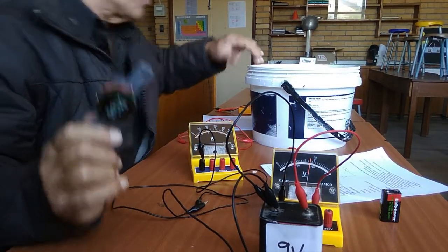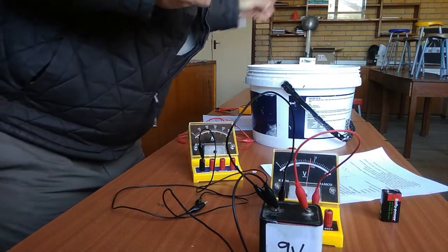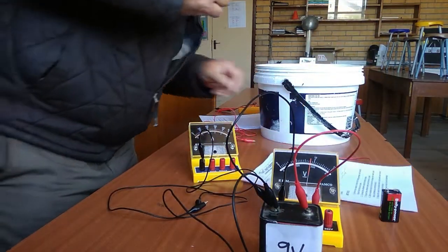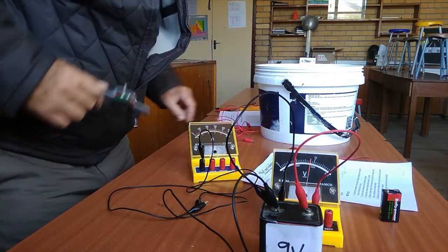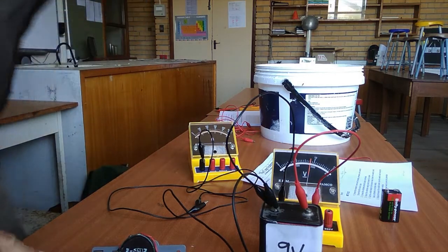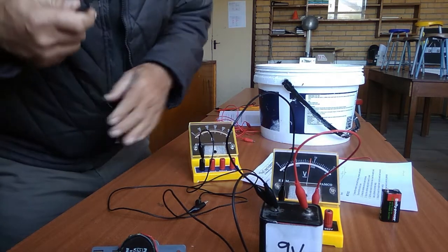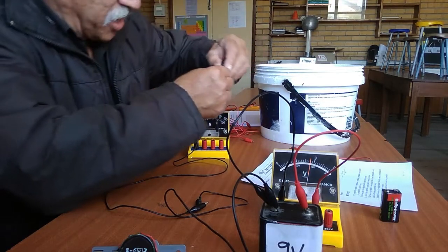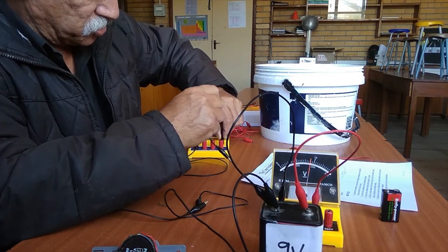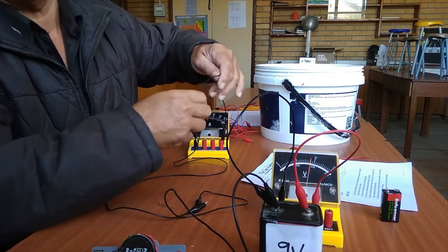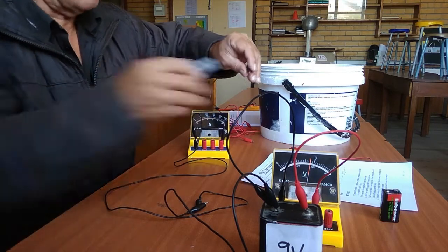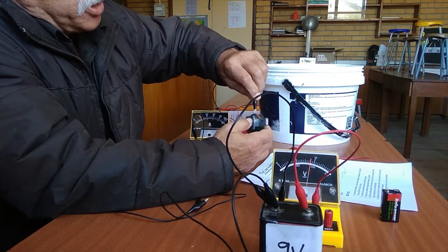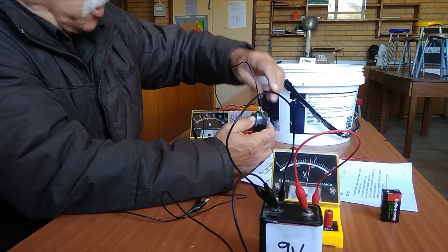So again, we're going to take a black lead. Have I got a black lead? Let me get another black lead. Right. So from here, we go from our ammeter. Now, our ammeter's got negligible resistance. I'm going to put it on the maximum, which is 5 amps, and I'm going to take it to the middle. It doesn't matter which one I take it to, to the middle.